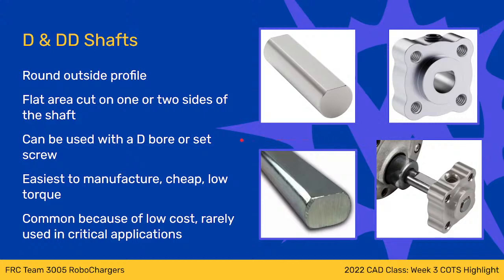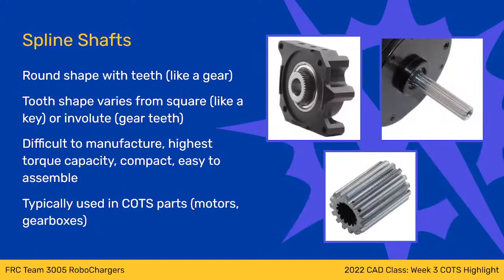We still use a lot of hex shaft in FTC though, because that's a superior torque transfer interface. All right, so let's talk about spline shafts. Spline is kind of a weird word. Spline also refers to a mathematical curve. They're kind of related, but not really related.